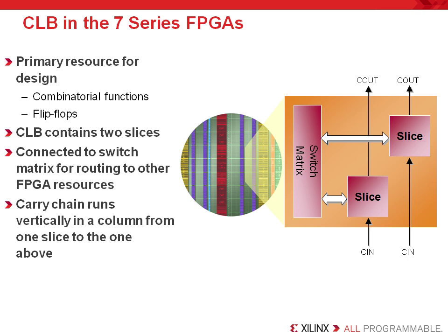The SLICE resources are the most essential and fundamental to an FPGA design. They include LUTs and registers. LUTs are built to create your combinatorial logic resources, and each has an associated register with it. The LUTs and the registers are grouped into slices, which also have other resources embedded in the CLB. Besides LUTs and registers, slices also have carry logic resources, which are designed to implement arithmetic logic functions with high-speed performance due to their dedicated carry chain, which runs vertically in columns from one slice to the neighboring slice.